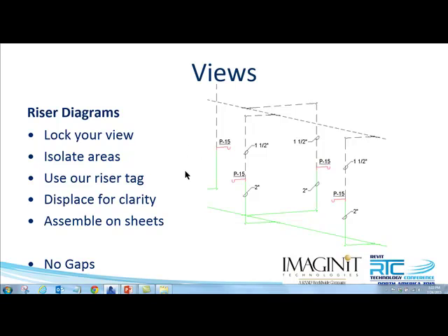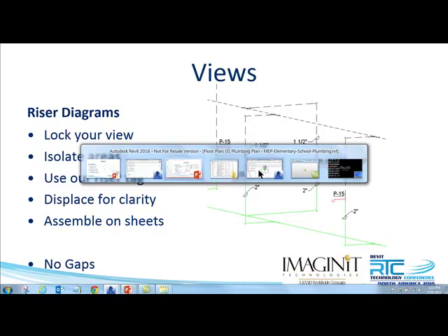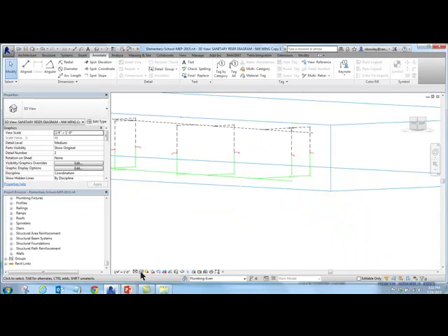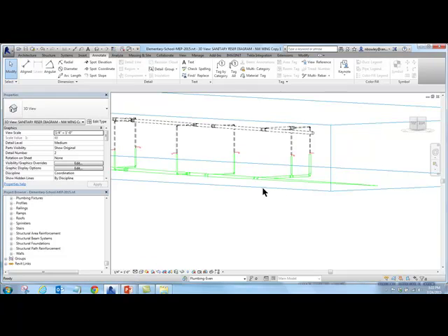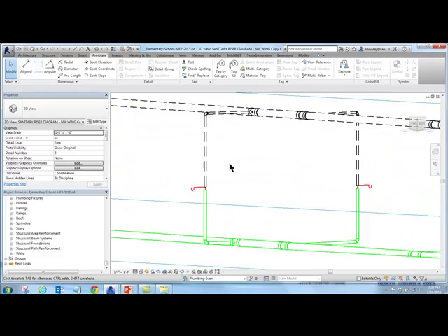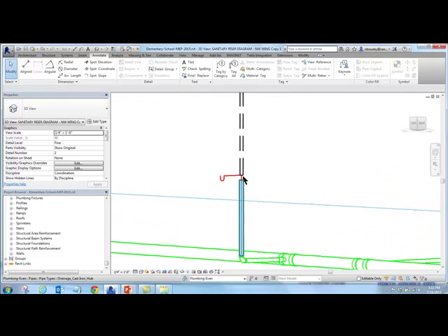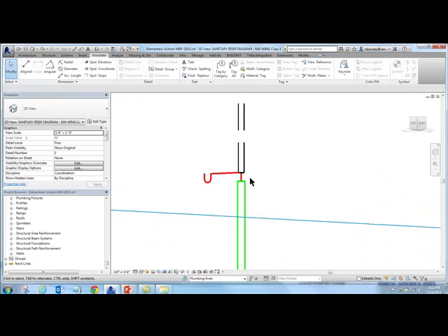We've been showing the risers actually in fine detail. Okay. Showing it 3D so then the valves show up nicely. Yeah. And also showing the architectural slabs with walls that are transparent. Okay. So this gives it more detail and keeps the floors on there. Yeah. So in that case, I might fix my fixtures up a little bit, but you can still do that and use something like that. You can even model this as a double line trap if you wanted to. Mine's just single line because that's what I used to do, but you could create a 3D trap, and you could probably use one out of the box.